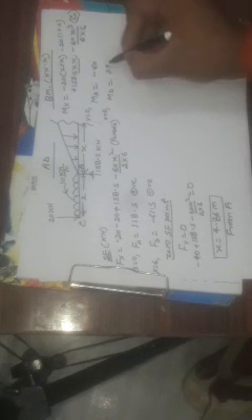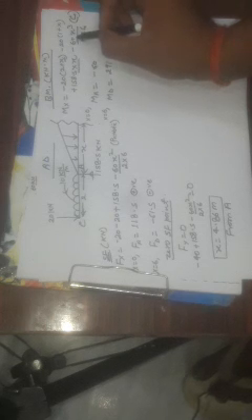And for x equal to 6, there will be point D, MD equal to, sorry, it will not be minus 12, it will be 291 kilonewton meter. Put the value x equal to 6 here, then minus 160, then 6 plus 1 is minus 140, it is minus 300, right? Here it will be minus 360, minus 660, and 158.5 into 6. Subtract this 660 value from this one, then we will find 291 kilonewton meter.